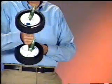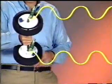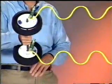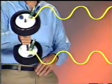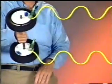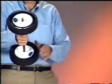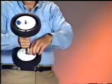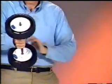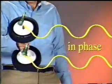If we mount a sensor at each end of the shaft to monitor the shaft's motion over time, they would record a trace of the shaft's unbalance. This trace would be a smooth sine wave for each wheel, but while one wheel is pulling up, the other is pulling down, so that the sine waves are moving exactly opposite each other, or 180 degrees out of phase. When the weights are moved directly in line with each other again, and the trace is monitored for each wheel, they would still be smooth sine waves, but now they are in phase with each other.